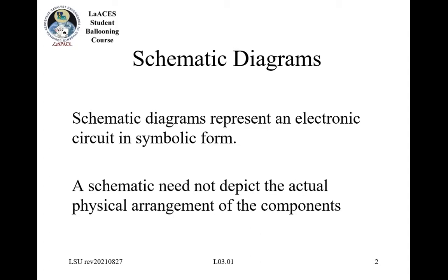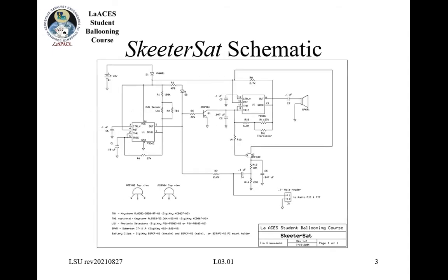It's very hard, especially on complex boards, to understand a board without a schematic. So if ever somebody gives you a board and says, here, figure this out or do something with it, the first thing you should ask is, where's the schematic? That's going to tell you how you should read and troubleshoot that electronic device. Some designs are proprietary, so sometimes it can be hard to get a schematic, but try to get that.